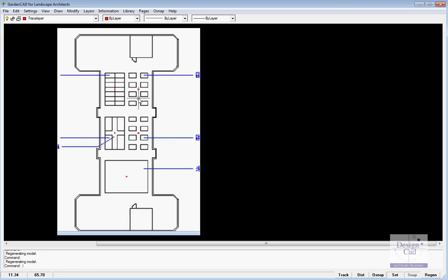of the white background. We'd want to make sure that tracking's on, so that if I draw, say, a line, can you see, as long as the indicator shows, we can get a horizontal line, because clearly these lines through here will be horizontal. And you might also check that you can draw a horizontal line and then go down at a 45-degree angle, because it looks very much as though that line there is going to be a 45-degree angle. So we're getting ourselves in a position ready to draw.